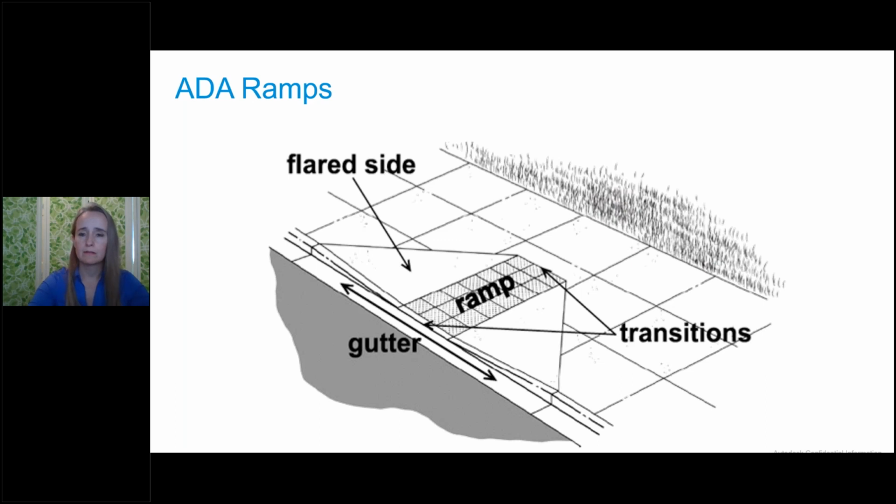And I'll just leave a little gap in my corridor that'll pull the feature lines from the normal curb section down to the ribbon curb section, and then back up as it goes through the ramp. And it works out really well for just modeling it for the surface. Have to get a little more detailed if I want to actually show the pavement in my corridor though. Okay, great. That sounds great.